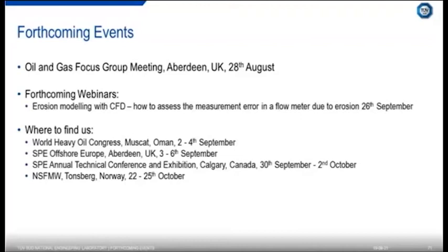Got a couple of others here. Somebody saying, if I'm calibrating a densitometer, do I need to worry about viscosity? Well, I did mention it in passing, and it really depends on the density measurement technique. For oscillatory densitometers, yes, because oscillatory densitometers are sensitive to viscosity as a second-order effect. The laboratory densitometers that we typically use, the Anton Paar densitometers, for example, have a viscosity correction built into them.